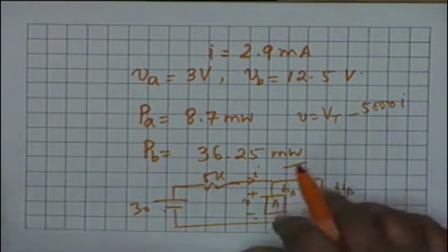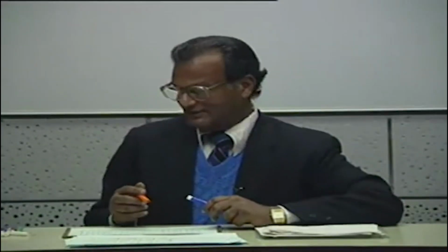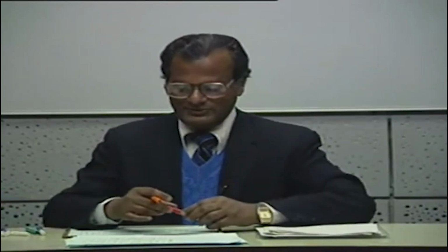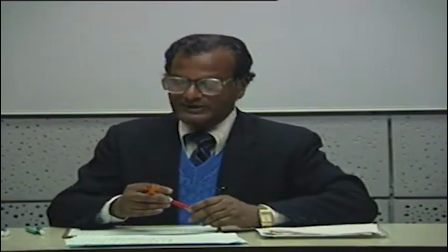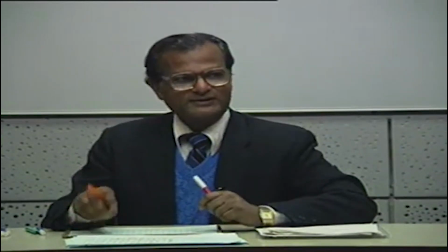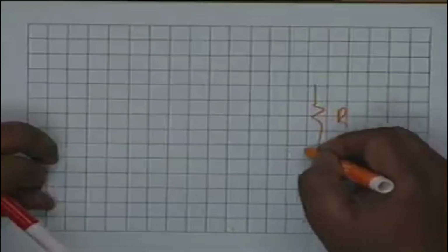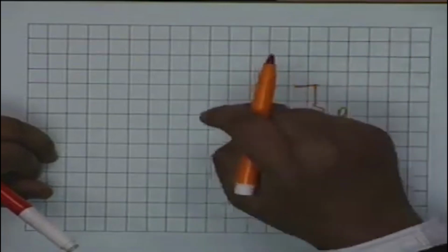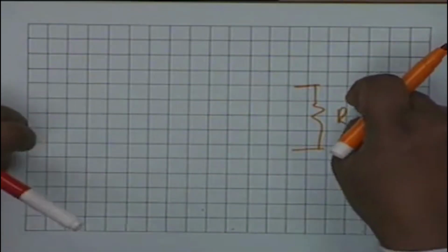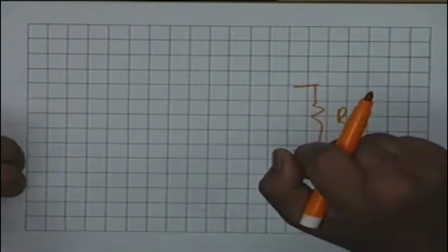Now one tricky question is about the superposition theorem. I told you that the current or voltage in any element can be obtained as the superposition of the current and voltage that would have existed if each source acted independently after killing all other sources. All right. Now, can I apply this principle to the calculation of power? That is, I have an element, let's say R, and I wish to find out the power consumed by R. I find the power due to one source acting independently. Why not?